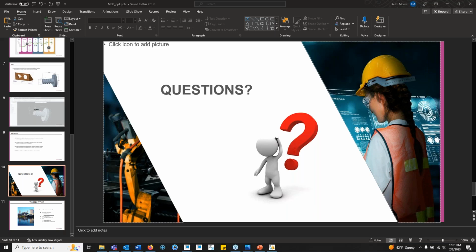Enrique, what is the difference between using the annotation feature to select references and just going to a 3D element? There is no difference, Enrique. It's just a personal preference. But I will say, with the dimensions that we are creating that don't exist on the model, that reference tab is grayed out. You select the initial references, and then you can furthermore add the references as we were doing in our file there. But ultimately, that's why I wanted to show the show annotations functionality, where that is available, and it ultimately does do the same thing.